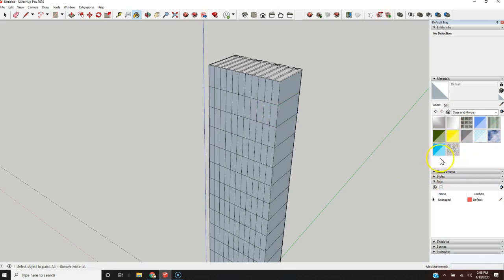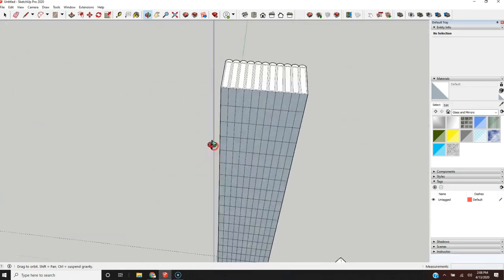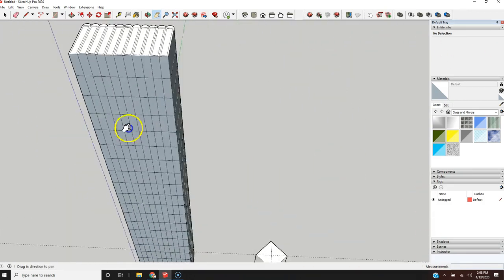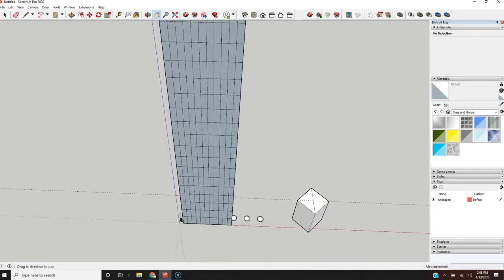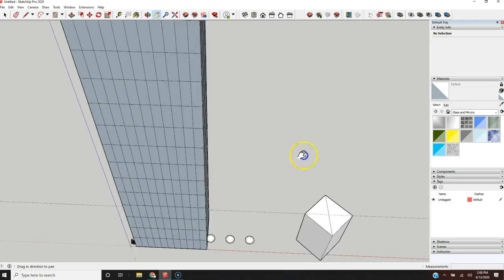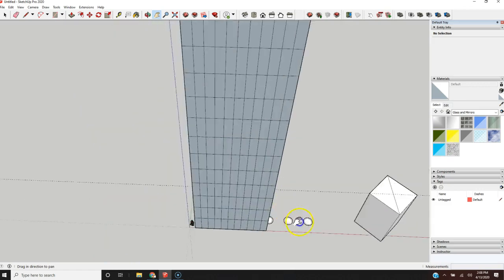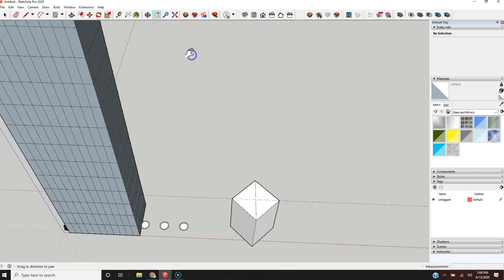If you tell me your computer crashed, I'm going to ask you, do you have all your materials up? It's on you. All right, this is orbit. Again, you just push your mouse wheel down and you can orbit. The hand tool is the letter H, and you're just moving it like this. And it's not zoom in and zoom out. Zoom in and zoom out, it's the wheel. Hand, you are kind of in the same scale, but you're just sliding things over from left to right, up and down, diagonally, wherever you want it to go. That's what that is.